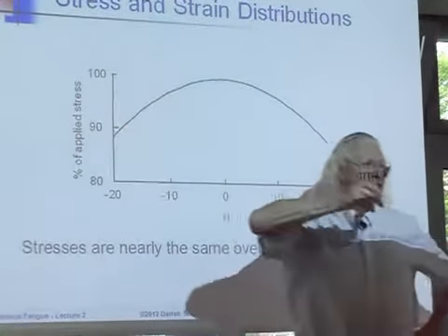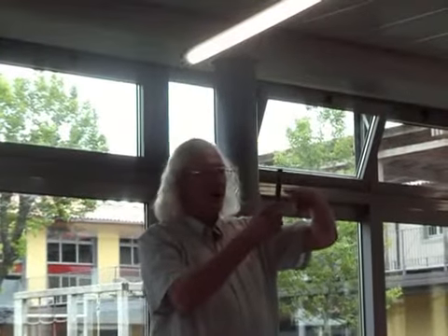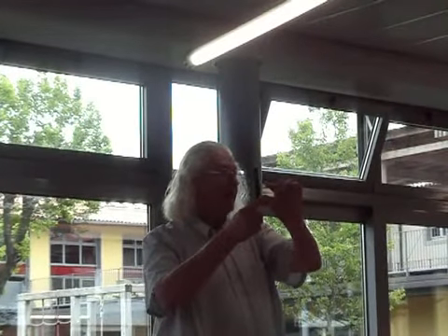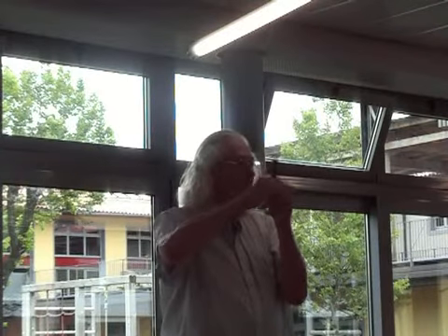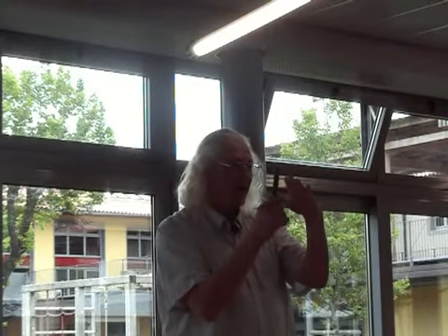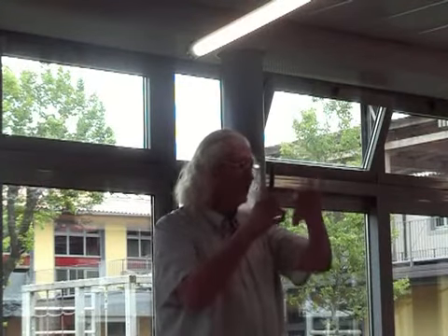So when I think about a crack growing somehow in a structure, and the plane it could grow on, it has a choice: plus 10 degrees, minus 10 degrees, because all those planes will have about the same stress. What will happen is the crack will choose the weakest plane near perpendicular, and materials are not truly isotropic. Materials are always a little bit different. So later, when I want to find the plane with the most damage, I think about the plane I calculate, plus and minus 10 degrees, because there will be no difference in the stresses until I move very far away, much, much farther than 10 degrees.